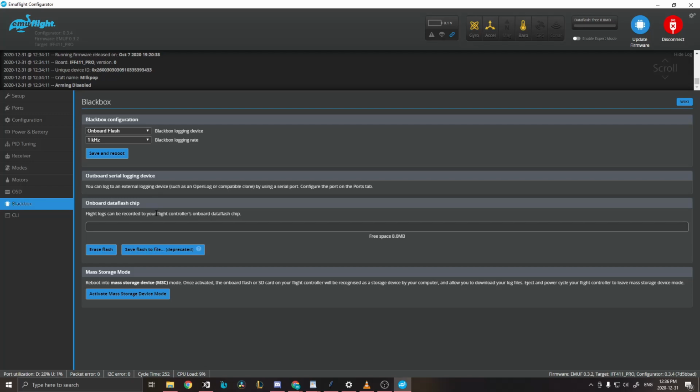I've got some ideas for this. I'll talk to some other people. We'll see what we can do with it. But anyway, now that you've got this erased, you're going to want to grab your quad, grab your camera, go fly a pack. Try to hit record and plug your quad in at nearly the same time, so your black box and your video recordings have similar start points. This won't be a problem if you're running a split type camera, as it'll power on when the quad powers.